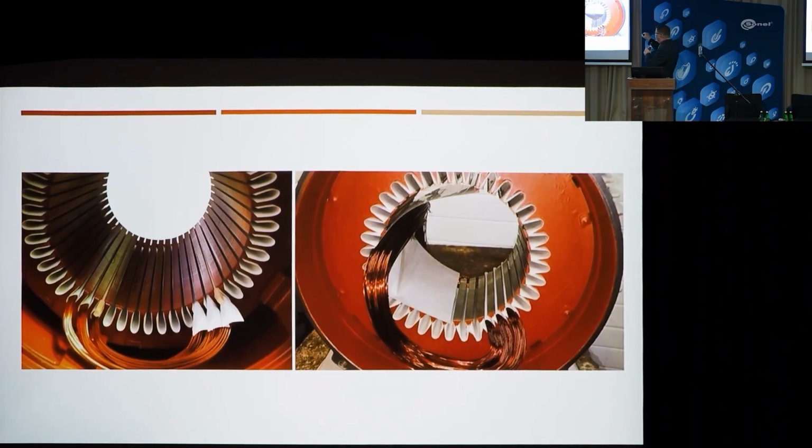And it turned out that those slot liners they slide into the grooves were made of pressboard in this case. One of them cracked about halfway down. And when she was tucking those coils in, literally 2 wires slipped directly between the pressboard and the slot.